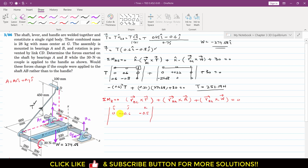And now we will write that T. So again I can write that T, this is 0.6 i and minus 0.8 j, and this is 0, and we can write that magnitude outside, right? So this is 251.19, and similarly we will write plus RBA, so the vector from B to A. So we can find that vector with i, j and k.